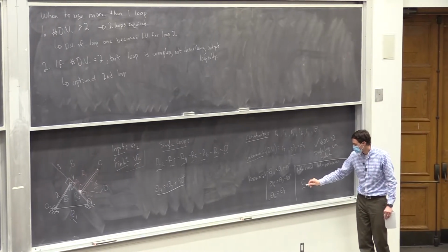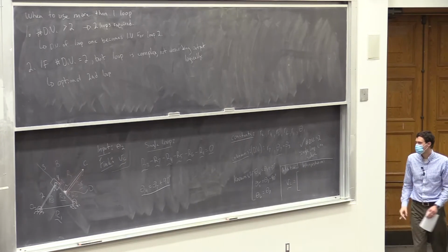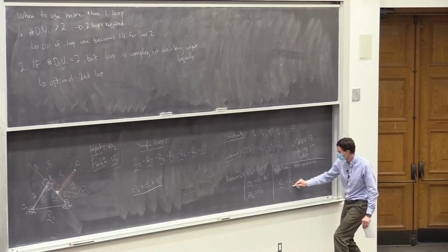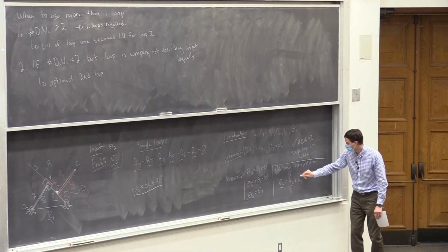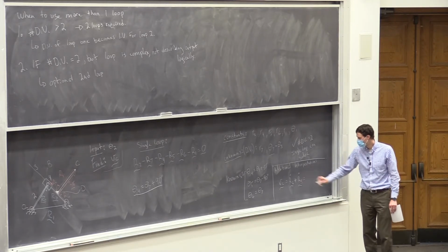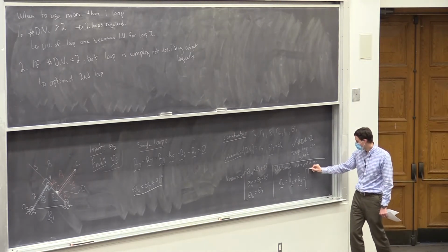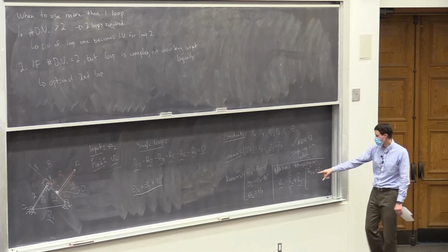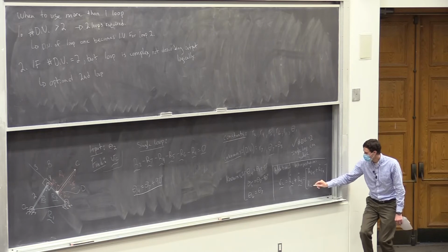So you could write out a vector for velocity of C. Well, one way you could write it is R6 dot plus R5 dot. So calculate those two. Or if you wanted to put it in the x, y coordinates, we don't have a great way of writing those. So that's the x coordinates, the horizontal components of R6 and R5 added together, and the y components.